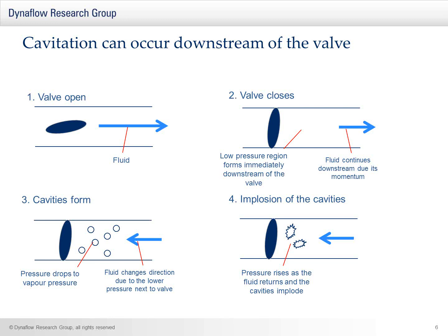The pressure in this region drops, and depending on the operating pressure of the system and the momentum of the fluid, the pressure can drop to the vapor pressure of the fluid. That means dropping to the vapor pressure, a portion of the fluid will cavitate to form gas bubbles.